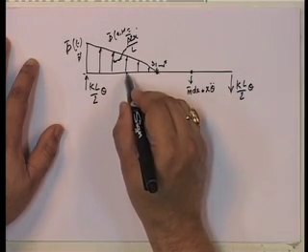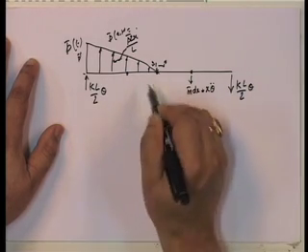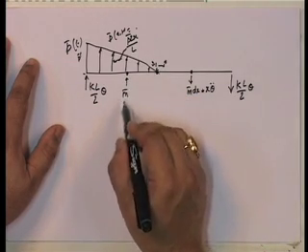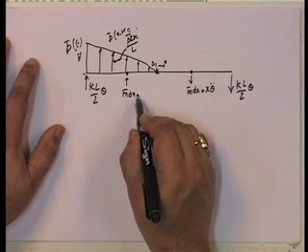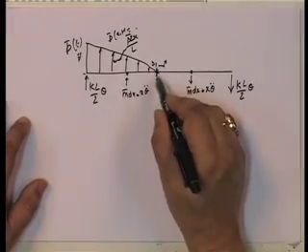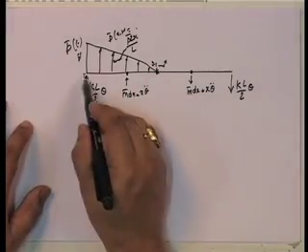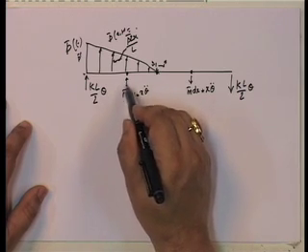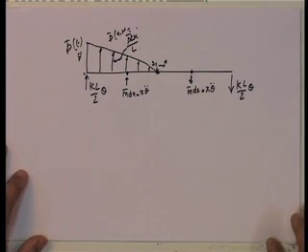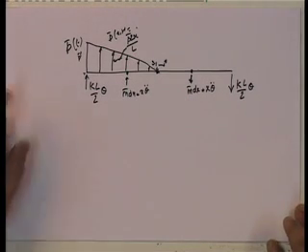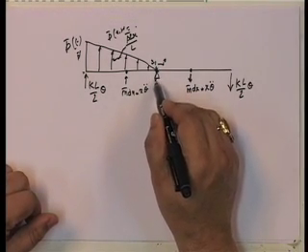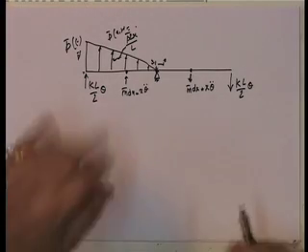And in this direction, since this is going down, this is going to give rise to m bar dx into x theta double dot in the opposite direction. So, understand that from here to here the inertial forces are upwards, and from here to here the inertial forces are downwards. This is a very important point to note, because this is rotating about this point. So, I have got all the forces.